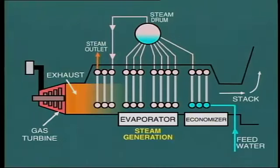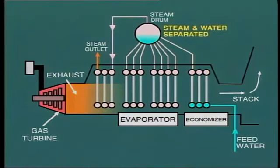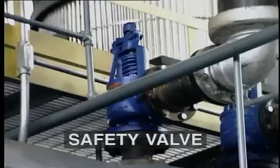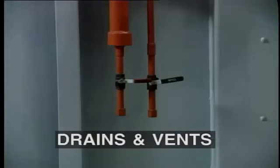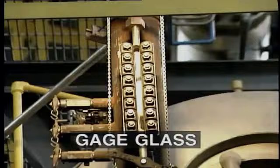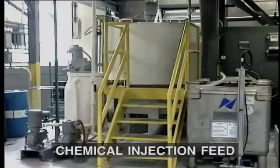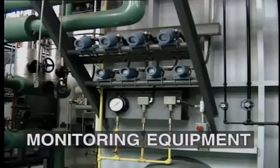The steam-water mixture returns to the drum where it's separated. Steam then passes out to the superheater where additional heat is added, and from here it flows to the utilization equipment. Also, similar to the fired boiler, auxiliary devices and equipment are fitted such as safety valves, drains and vents, gauge glasses, water level controls, continuous blowdown line, chemical injection feed, monitoring equipment.